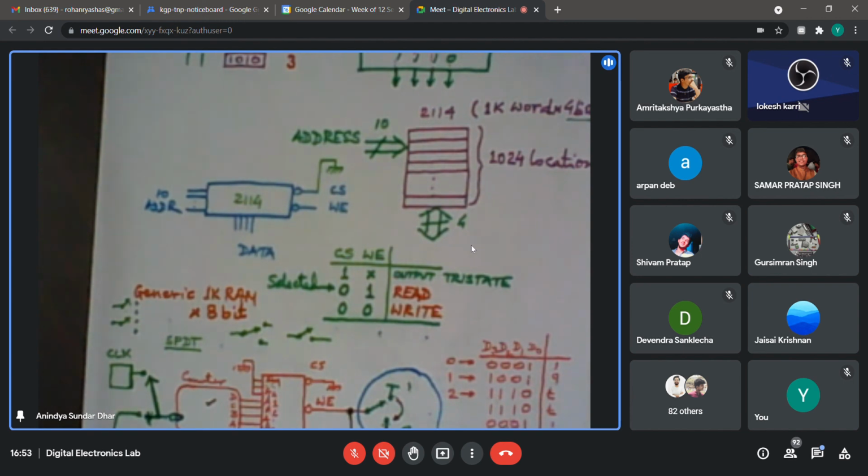So it says it's a generic RAM structure. It is not specific to any commercial product. It says a generic RAM 1K into 8-bit. But I find it is very closely related to that 2114, excepting the bit width. So you may choose that: device, browse, digital by function, RAM, then generic RAM 1K. Okay, sir. Thank you, sir. Okay, so then I'm closing the meeting now.